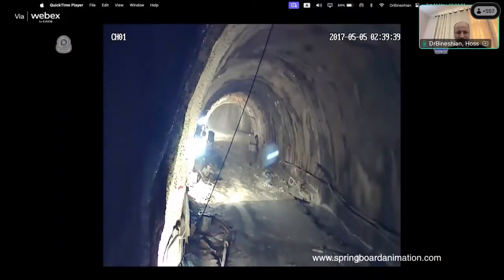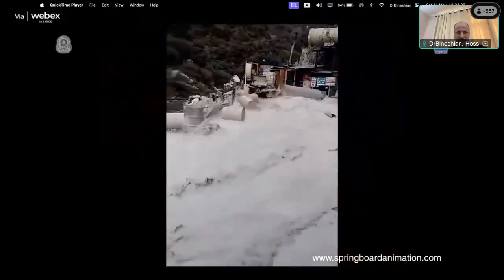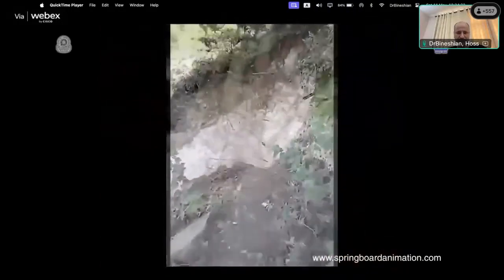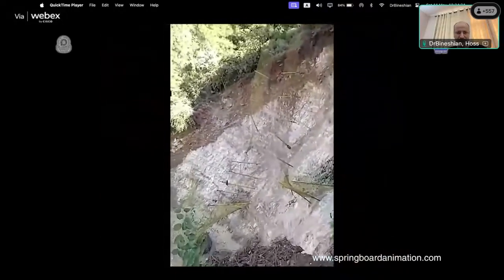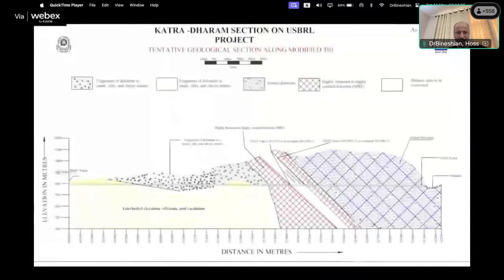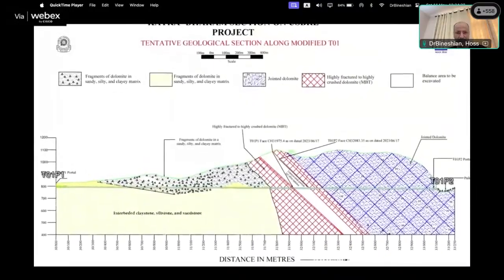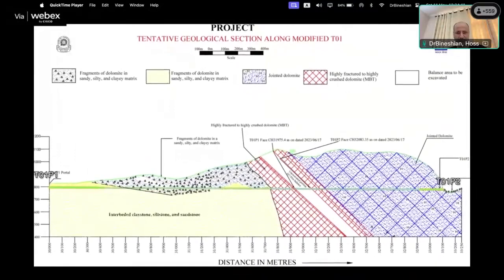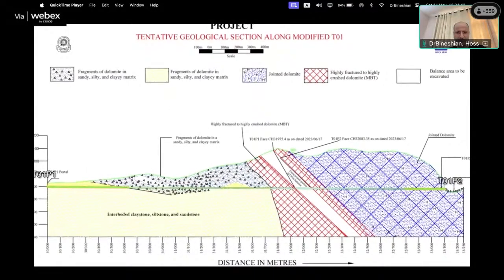Faces, at the above chainages, discharged a high-pressure mix of debris along with water, containing fully saturated, crushed and sheared dolomite, scree, and alluvium and colluvium in a matrix of calcite, clay, and silt. This is the entrance of T01 to the RT portion of MBT of the overcritical wedge of the Lower Himalayas from both ends.